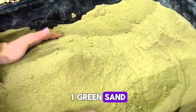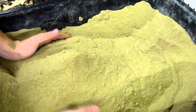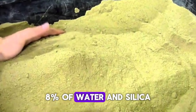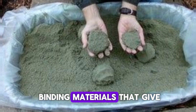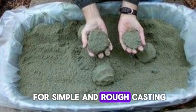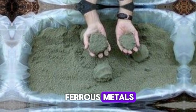1. Green sand. These types of molding sand are natural sand with enough moisture in them. It contains clay of about 15 to 30%, 8% of water, and silica. The clay and water act as binding materials that give strength to the mold. It is used only for simple and rough casting. It is used for both ferrous and non-ferrous metals.